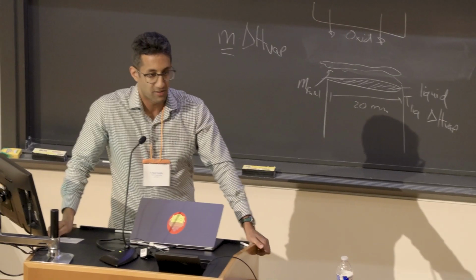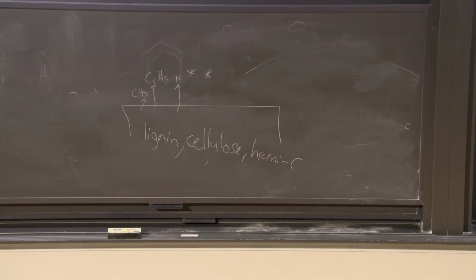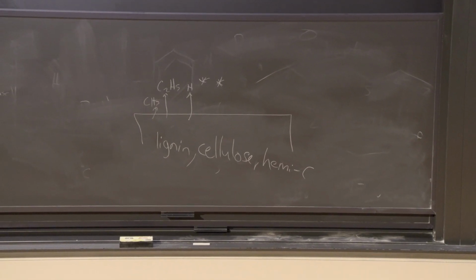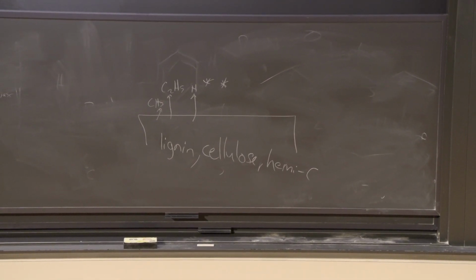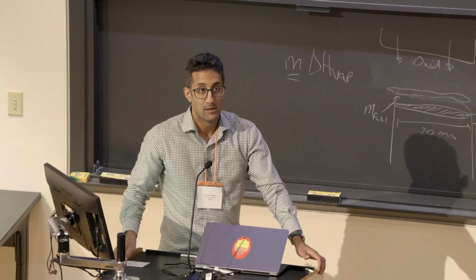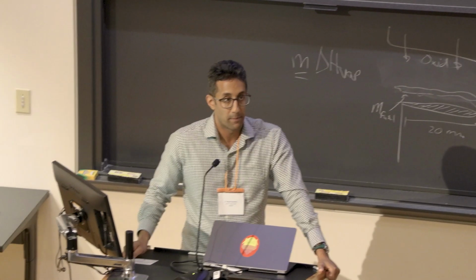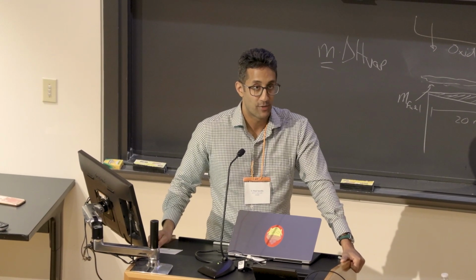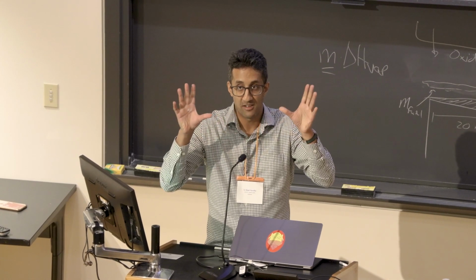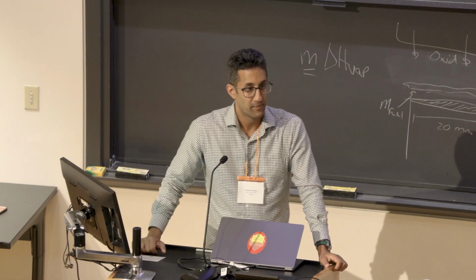What happens in the burning process? Well, of course, this biomass pellet has to be heated up, but the kinetic approach is to assume that most of the important reactions happen in the gas phase. So the first step is what we call devolatilization, devolatilization of the solid material into the gas phase. The same thing with vacuum residual oil. We are trying to model the gas phase reactions that happen after the initial volatilization of a heavy liquid. And the same is true in the biomass.